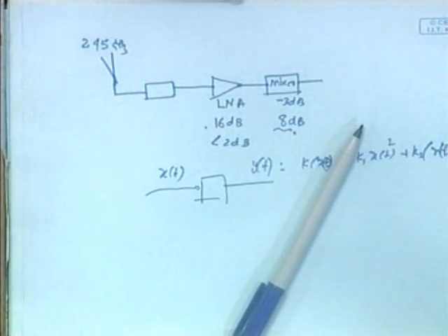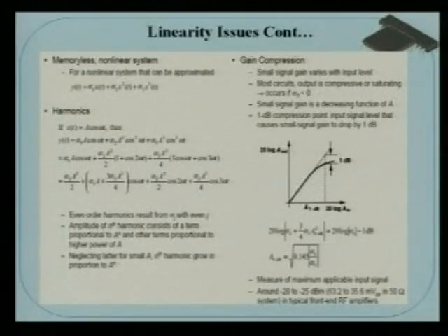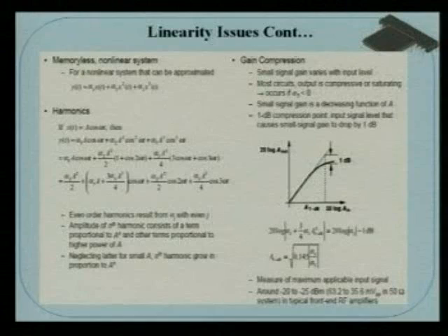So this cos square or sin square term will contribute to the harmonics. If you take sin square omega t, what does it mean? It is cos 2 omega t, that way you can expand this. And you can also expand this term with intermodulations, I will show later on. So that is the reason why you will find harmonic content for nonlinear devices, because apart from the first order approximation, the linear term, you have the other quadratic and cubic terms too. And if you square or cube that, then you find that harmonic content.